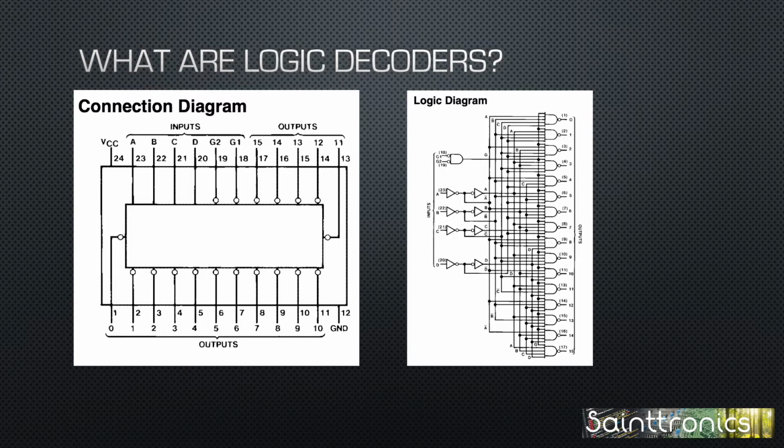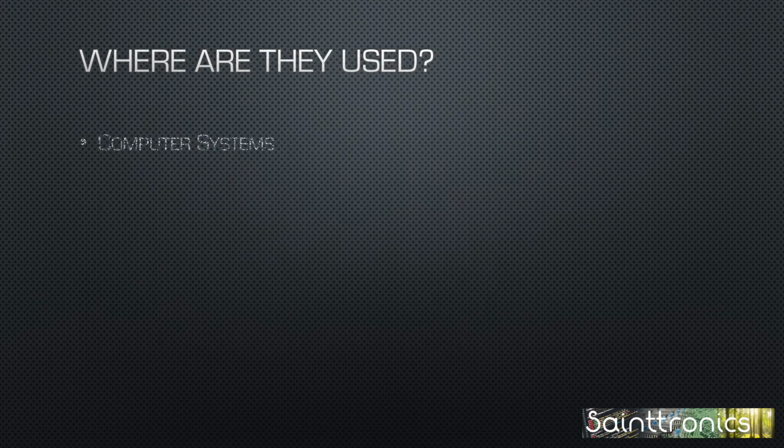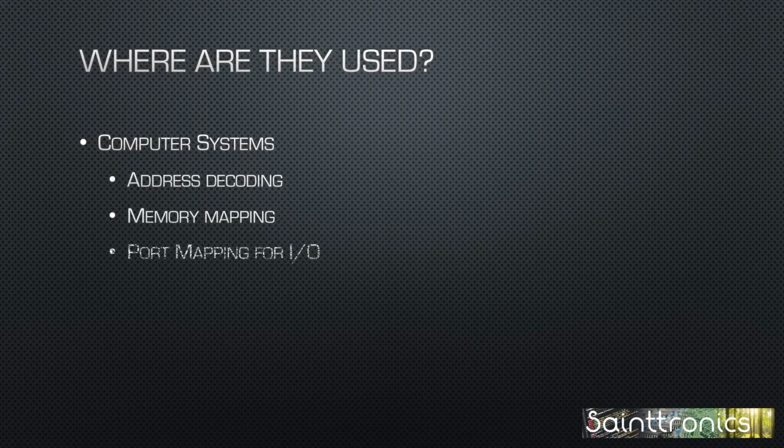It's not uncommon to see two 74LS138 decoders linked together to generate a 4 to 16 line decoder. This would mainly be a cost cutting exercise, as the 74LS138 is very cheap compared to the 74LS154. So where are they used? As mentioned earlier, these chips were found in many computers from the 70s and 80s, before programmable logic ICs such as PALs and GALs were used.